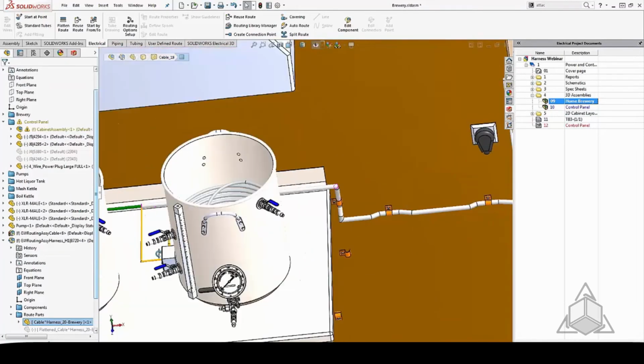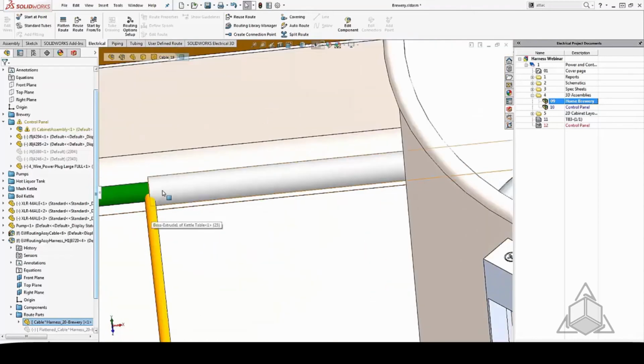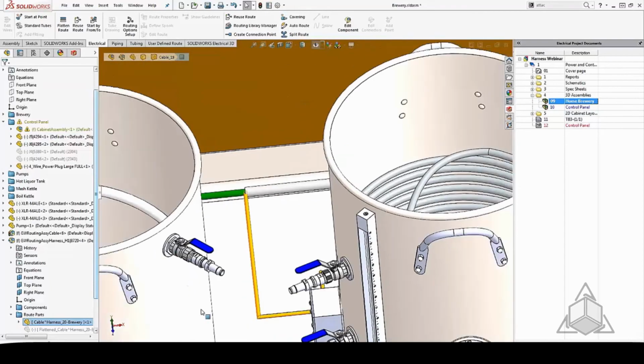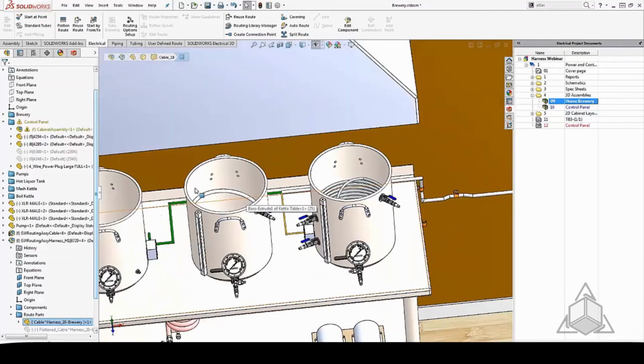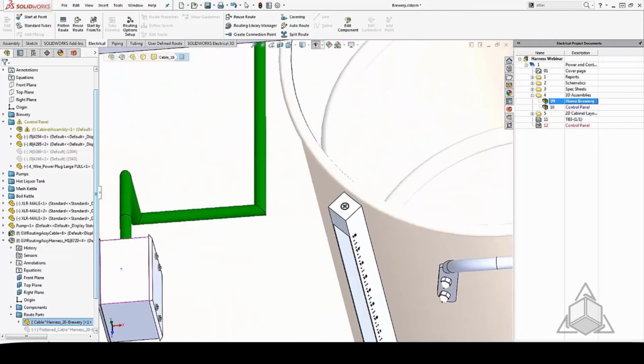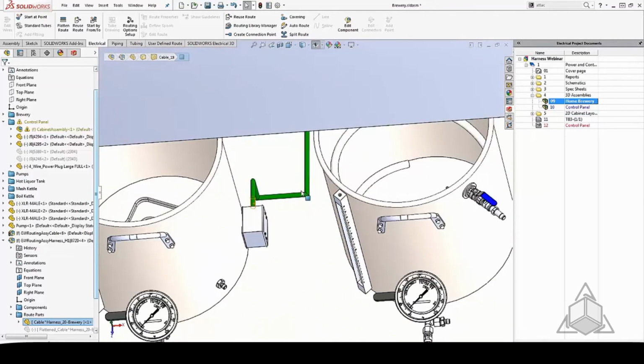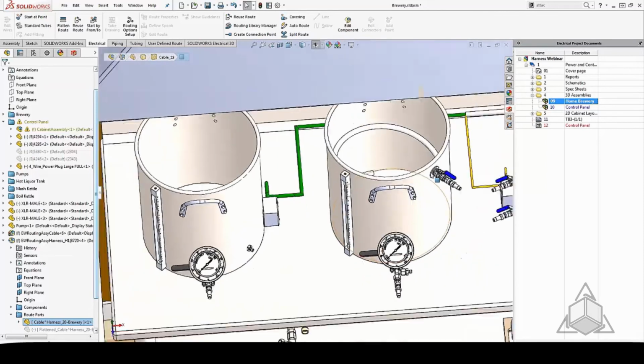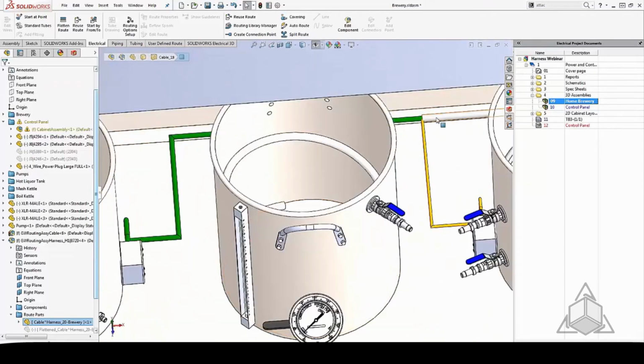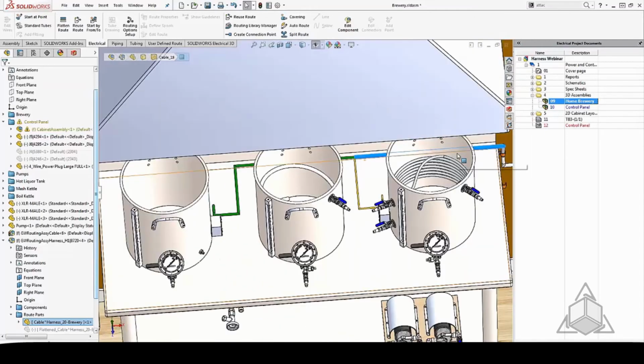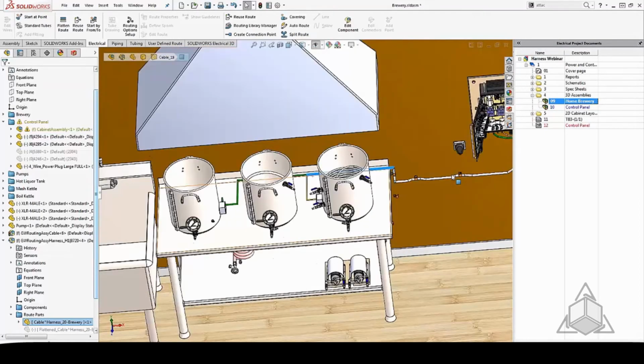However, when the cables need to split out of that harness, it's going to generate its own path. This is the last common area that we're sharing between these two cables. My orange cable is going to split out to kettle 3. My green cable will continue behind kettle 2 and run into kettle 1 here. So we can start to see these different colored cables that join in the harness. Once that harness is routed, we can actually isolate it.